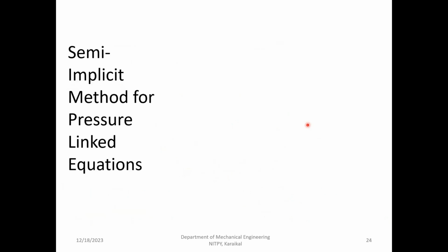And one more thing we'll be using is pressure and velocity coupling. When you have flows, this came up with an idea when people were thinking: we are going to put pressure and velocity at some particular points, the cell, and then calculate it. What if we get an unphysical phenomenon? That is, the point has a pressure of 50 Pascal, and on either side it has a pressure of 100 Pascal. That will be called a checkerboard pressure field.